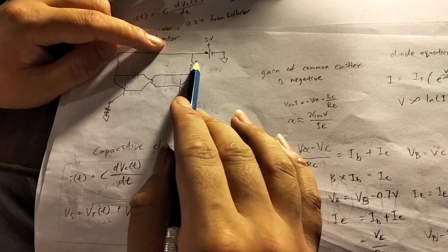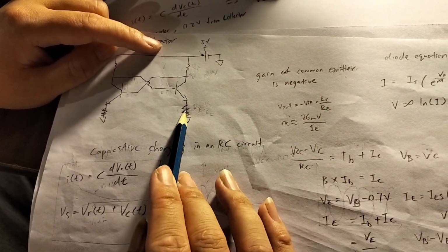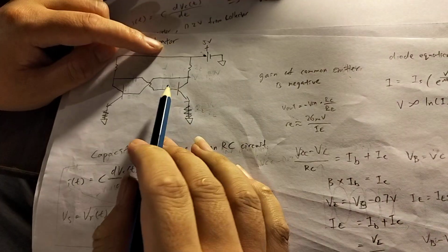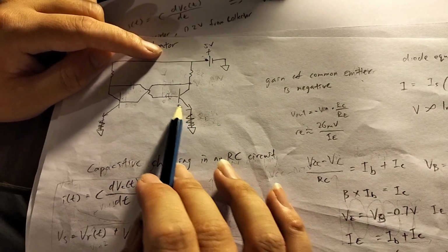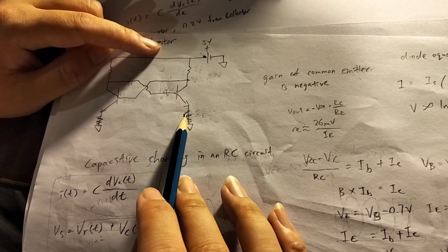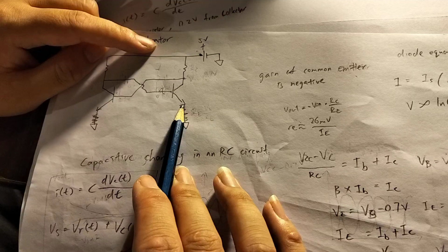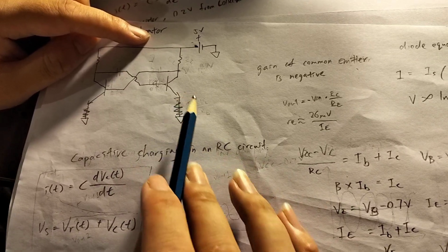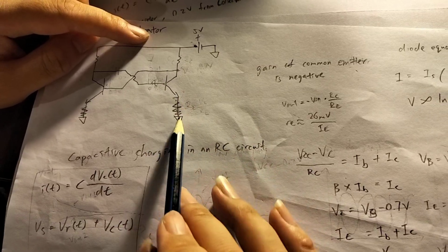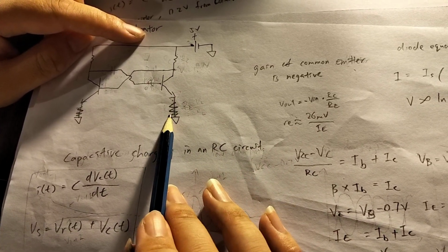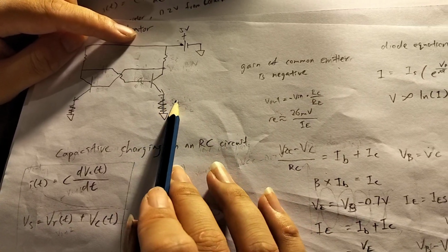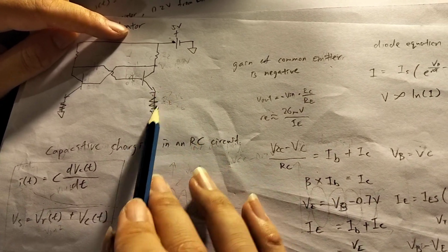Now I'll quickly run through what this amplification really looks like. When the RC over RE ratio becomes bigger than 1, let's say a small signal comes through RB and increases the voltage a little bit at this base. The base-emitter voltage increases, and the current in the emitter increases by V over RE.